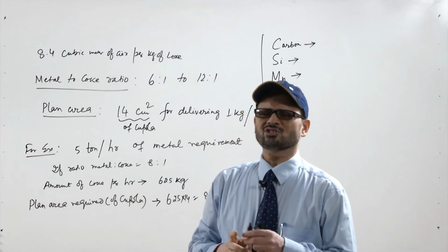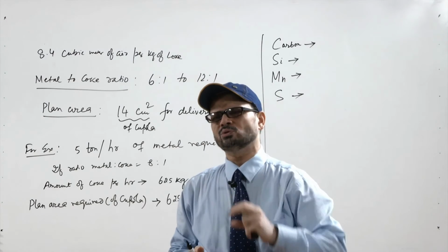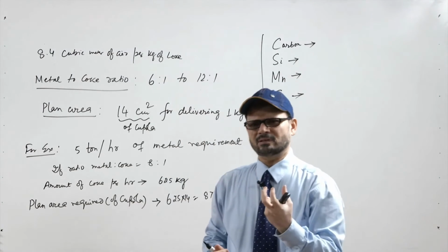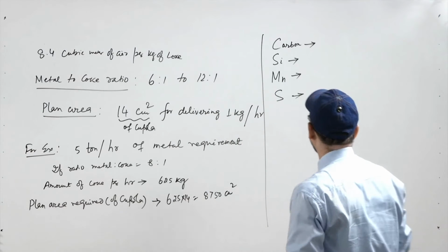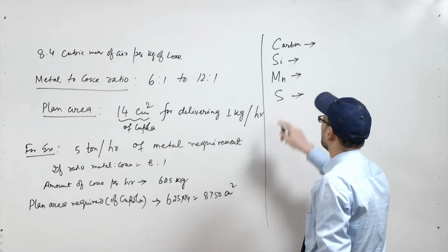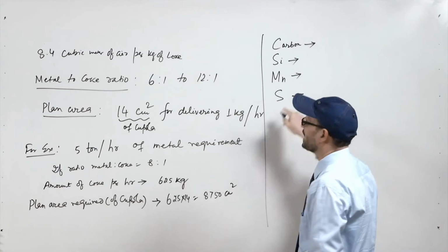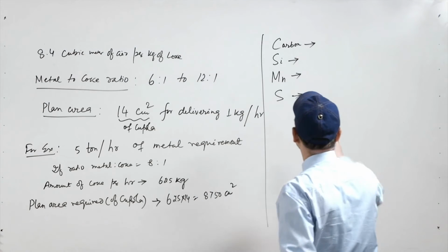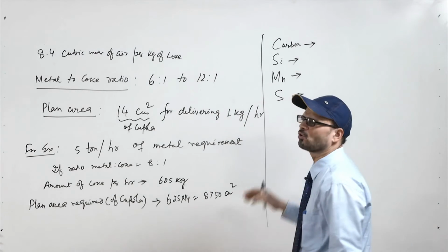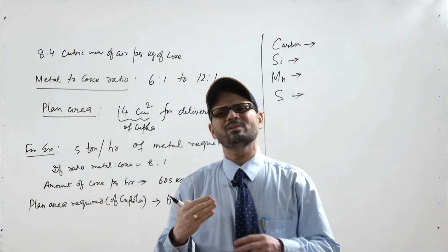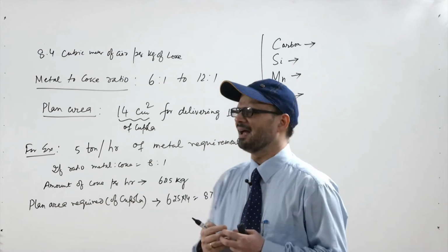Because the coke which we use has sulfur, the melt picks up this sulfur. That is why you have to see what kind of charge you provide, so that there is not much sulfur. It will depend upon the type of coke you provide. If the coke has a larger amount of sulfur, there will be a larger pickup of the sulphur, and a large amount of